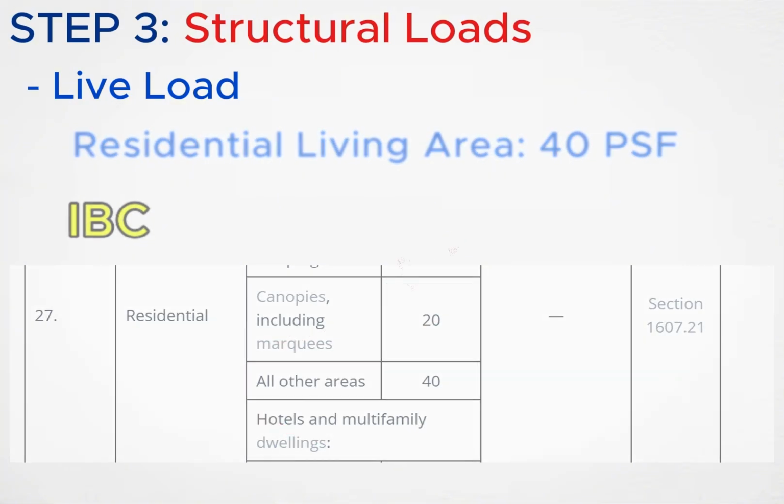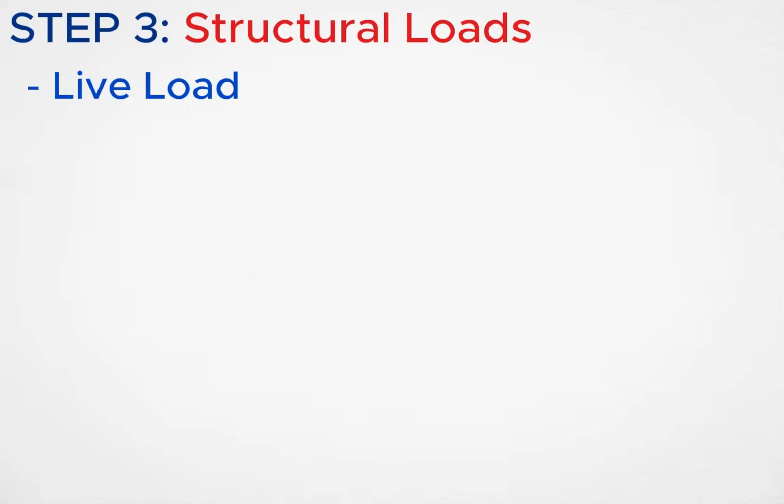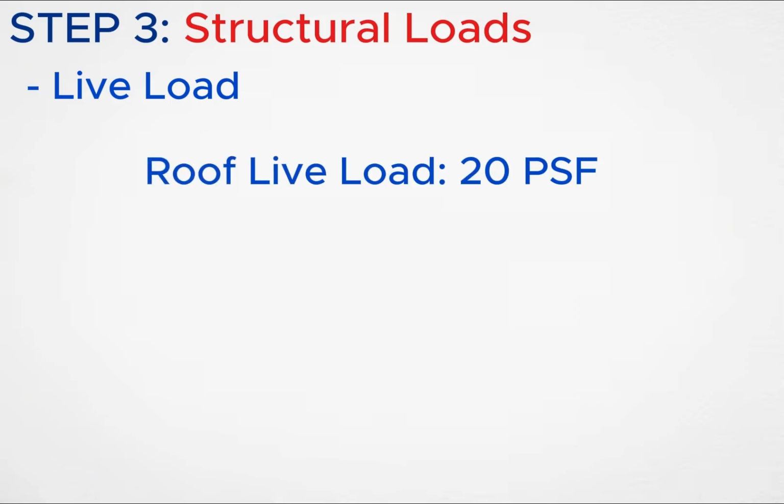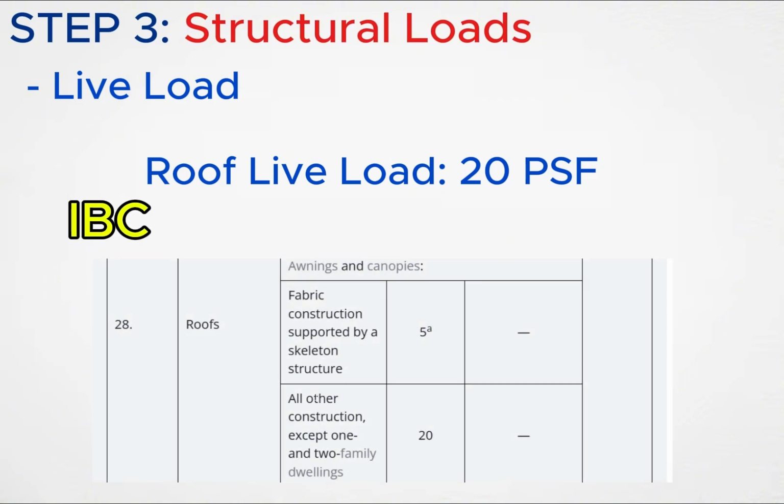Roofs can also have live load. This is called roof live load. For many residential projects, roof live load often starts at 20 pounds per square foot. However, the actual design requirements should always be verified using the applicable code.